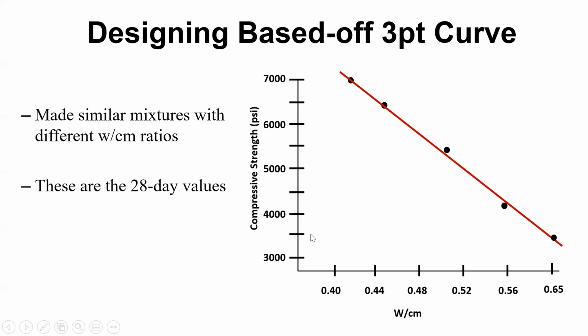and say, okay, so I don't have any data whatsoever, so I need to be at least 1200 PSI as a safety factor. So you can go through here, figure out, okay, where do I need to be for 3000 PSI? Well, I need to be at 3000 PSI plus a safety factor, come over, okay, there's my water cement ratio.